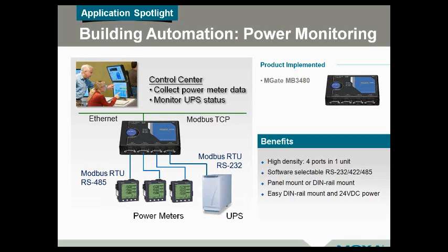And even today, and I'm using the example of a formerly Square D here in North America, known now as a Schneider Electric power meter, these are new devices. They don't have an Ethernet port, and you can only get at them with a serial connection. So if you want to get at these more than a couple thousand feet using RS-485, you need to have some way with which to do that. Here's a great solution by being able to tie that together and bring in those assets from your sub-metering within your panels, back into a control center where you can monitor what's happening.